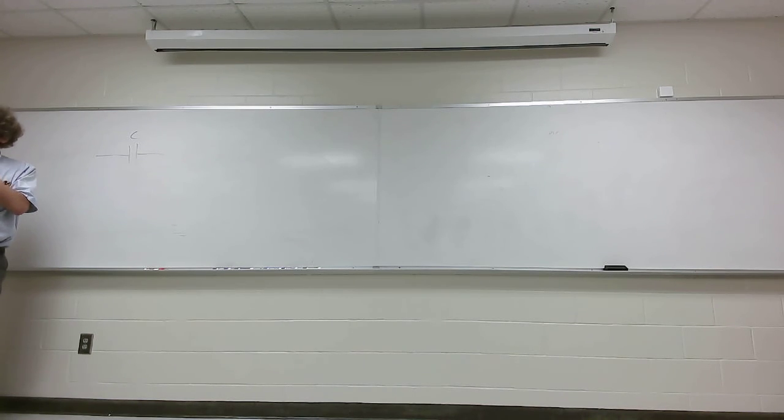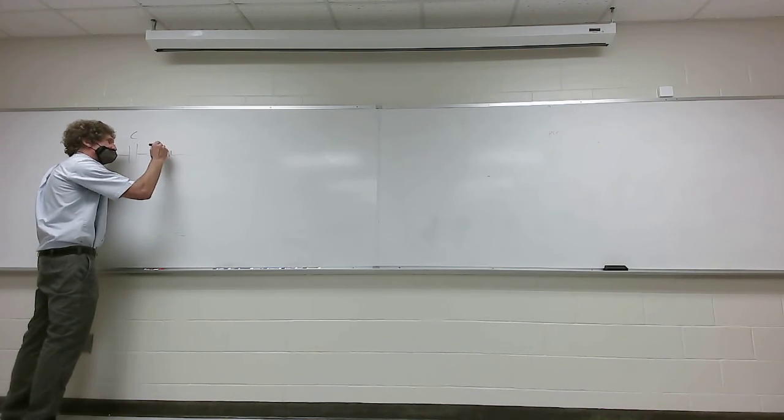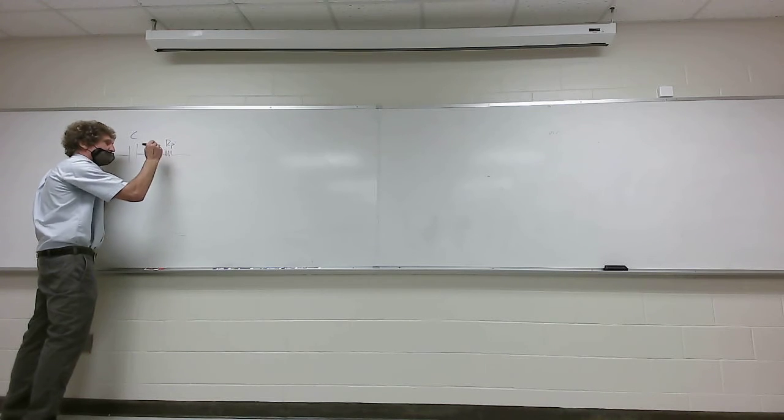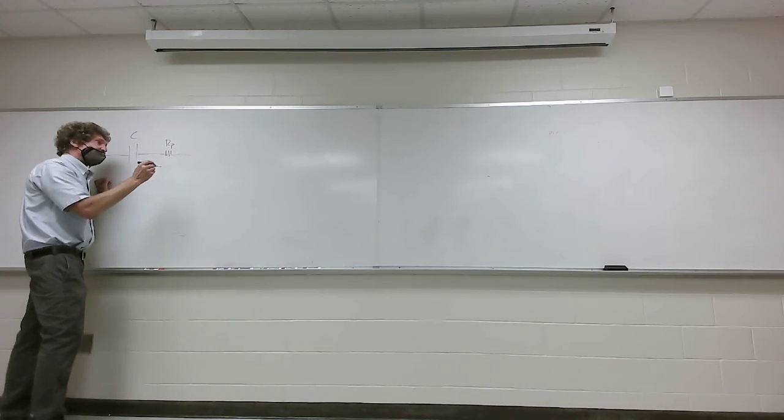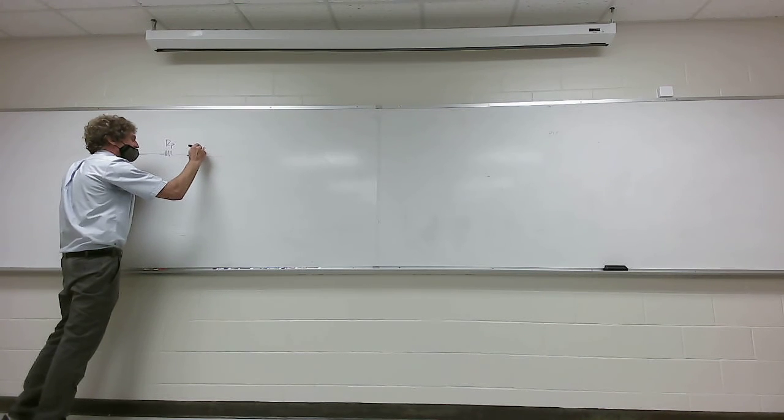The standard way for most disk and low loss capacitors, this is not true for electrolytics, is this way. You start with the capacitance. Now, anytime I have current and I have a wire, I have inherent resistance based on that wire. So then you put a resistance like this. You can call it parasitic, it's unwanted. And then you're also going to have L lead.